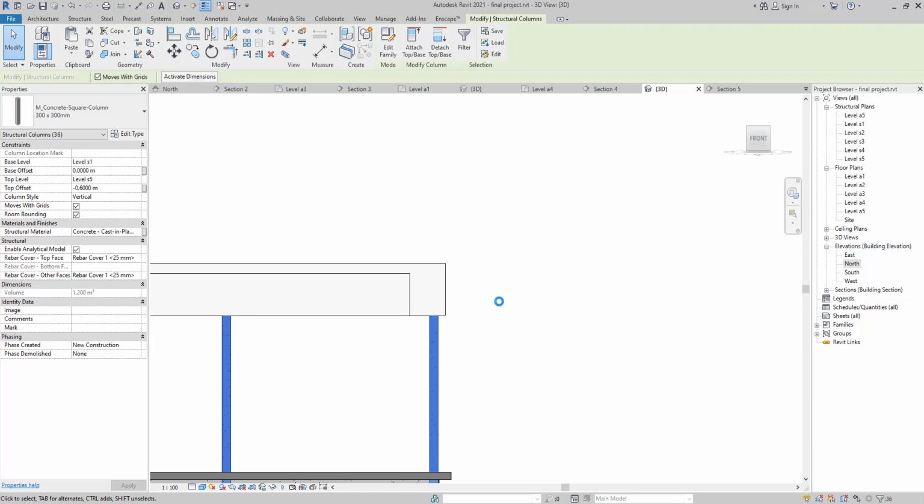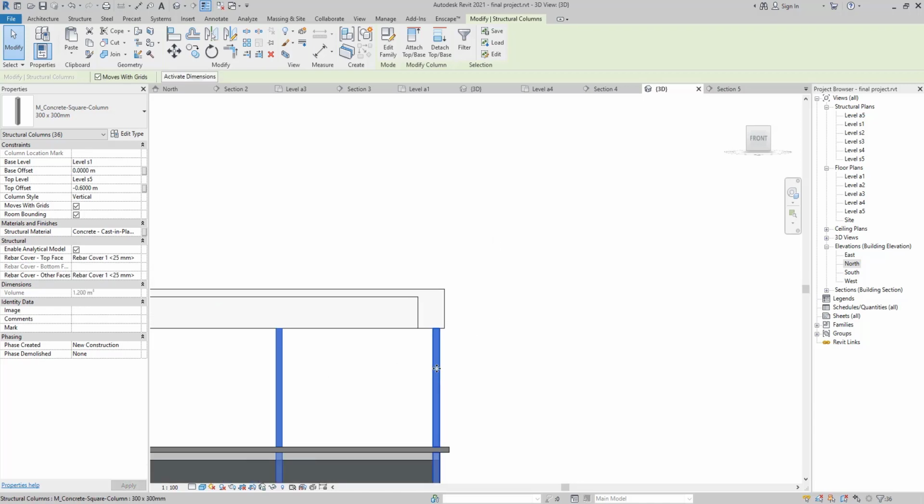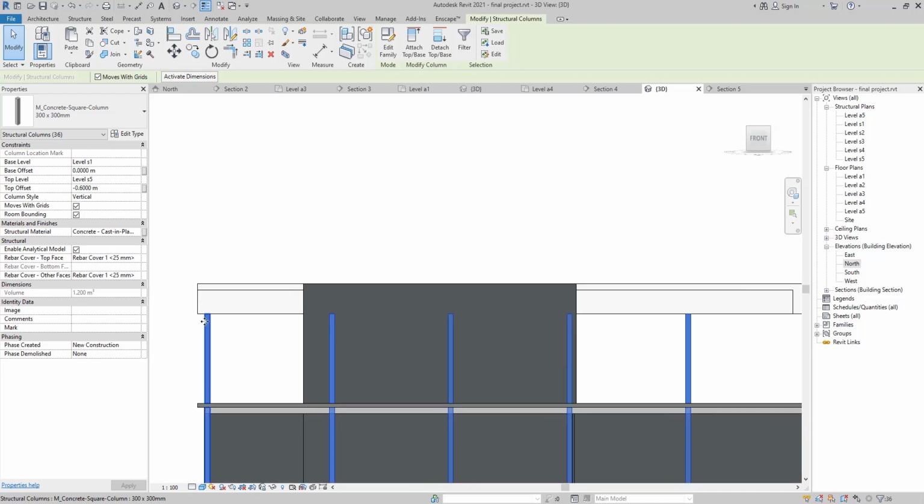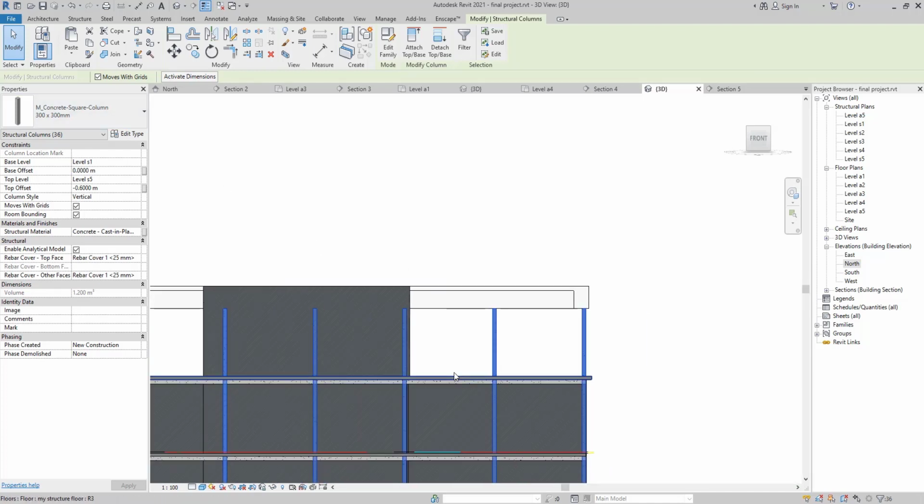We are going to fix our problem by setting our minus 60 centimeter. But there is a point here, since I'm going to design some elements on this roof later on, and I need to have these columns, because the purpose of bringing the columns was not only visualization but also supporting my roof element. So I need to take these columns up to reach the roof, because we have a void here and we use this void.